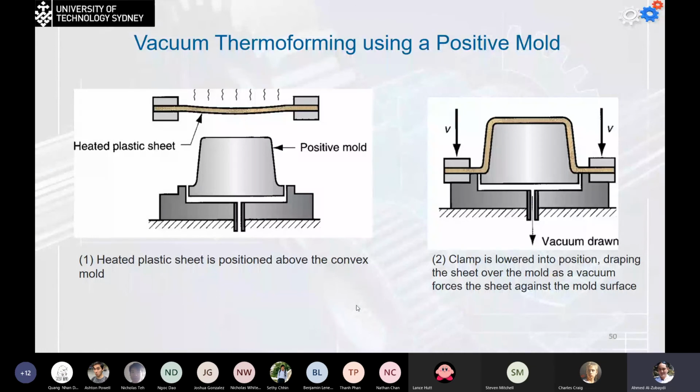And usually when you use it for thermoforming, they didn't show that in the previous videos, but actually we need to add some talc powder on it, so we're not going to have the sheet stick in between both, especially if the shape is going to be quite complicated.